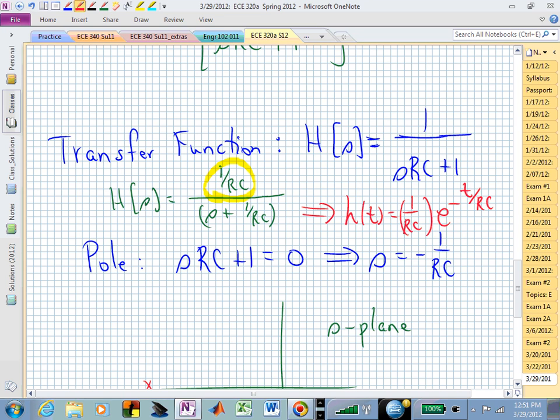And we're going to call that the impulse response, and we'll make that more clear in a few minutes. But that's now the impulse response of this low-pass filter. So what is the impulse response? If I went up to that circuit and hit it with an impulse, this is how it would respond in time. If you applied a voltage source that was an impulse, the y of t, the output voltage across that capacitor, would behave in time like that h of t.